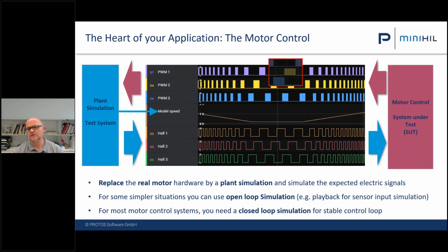Some simpler simulations you can run with open loop. For example, a playback force for a sensor input like a temperature or something like that, that can be done in open loop. And for most motor control systems, you need a closed loop simulation for a stable control loop.